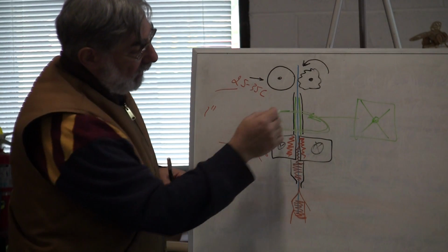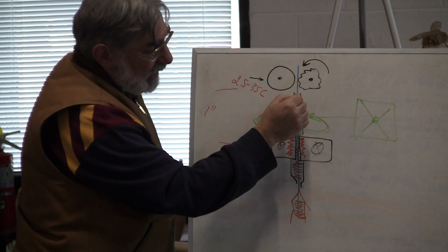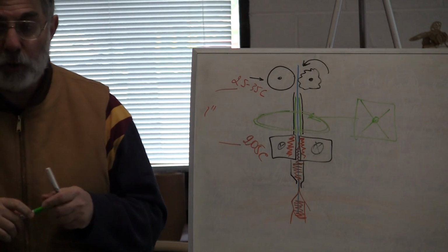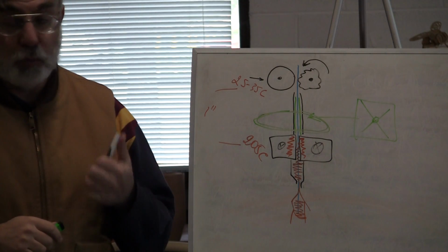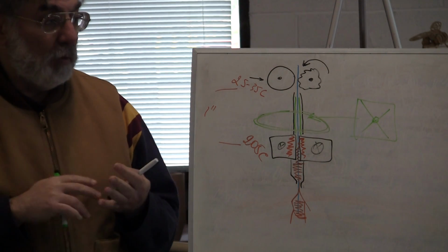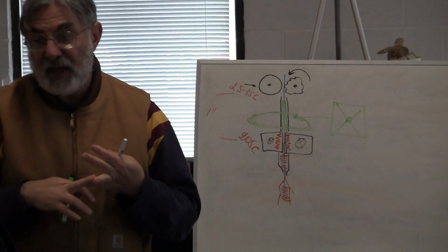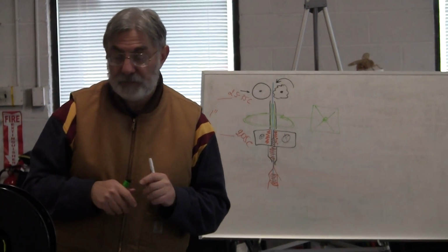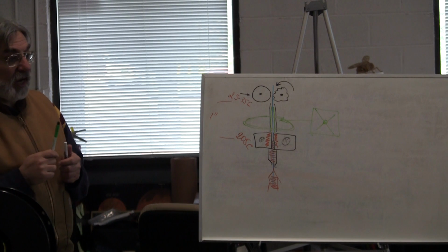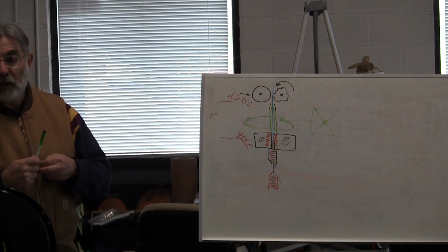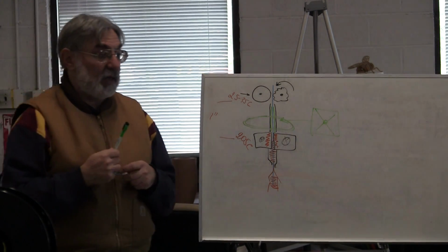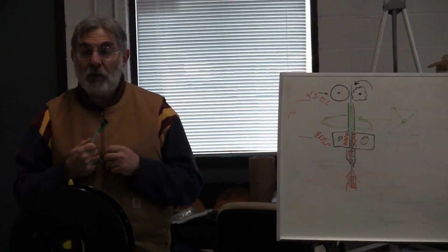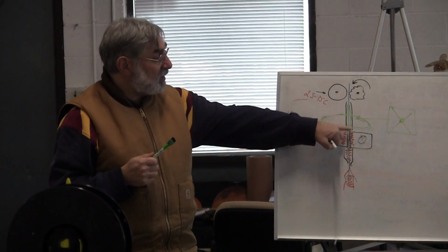So here's what's going on. That tubing inside is made out of Teflon. For lower temperature printing, that works really, really well. For when you're printing with PLA and ABS up to about 230, 240C, that works. The problem starts happening if you want to print something a little hotter, like nylon. Nylon requires printing temperatures so hot that the Teflon inside starts melting.